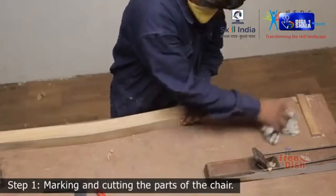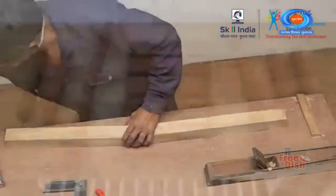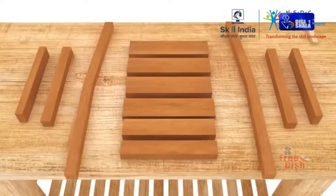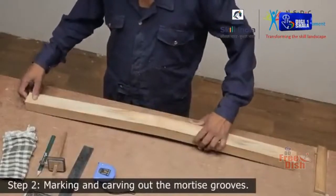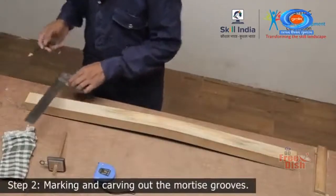Similarly, mark the layout for the other legs, framing pieces and support rails, and prepare them according to the dimensions mentioned in the table. After you are done with cutting the parts to size, you need to carve out the mortise and tenon joints for joining them together. Measure and mark the points where your backrest, framing pieces and support rails would join.